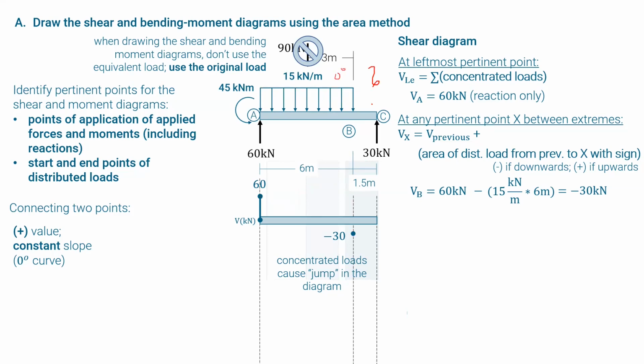Ito yung magiging reference mo, no? Yung previous diagram. Kapag nag-draw ka ng curve ng shear, yung reference mo is the loading, okay? So you see here a constant slope, tapos yung value niya is pababa. So that's a negative value. Okay? So dito, kapag positive value and constant slope, ganito dapat yung itsura ng curve. Kapag negative value and constant slope, ganito dapat yung itsura ng curve. Okay? So sa case natin, again, this is a negative value, this is a constant slope.